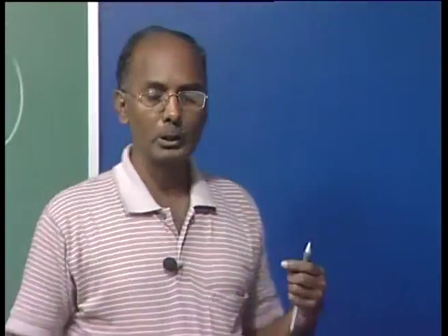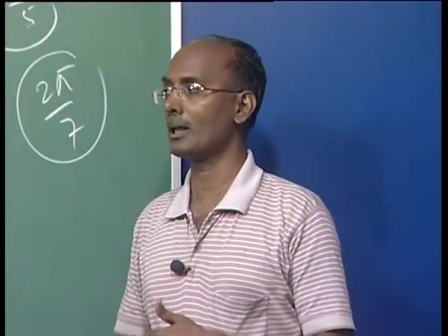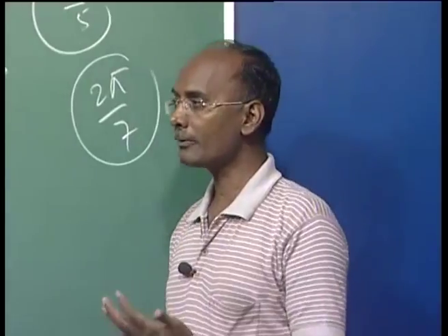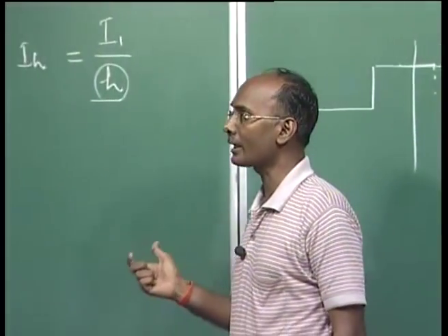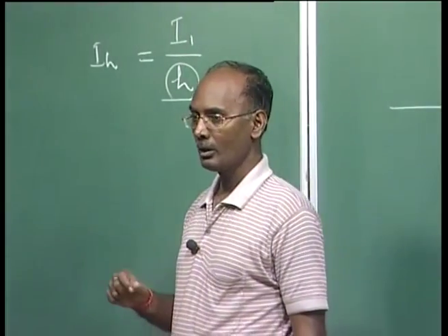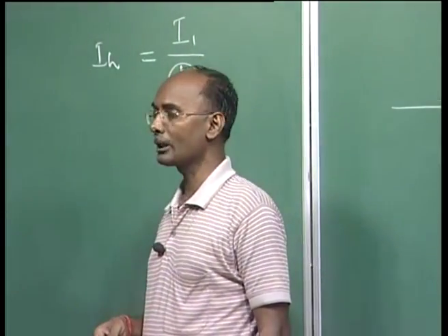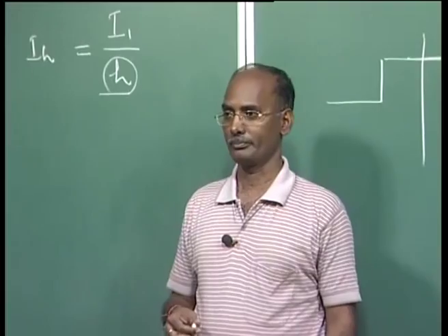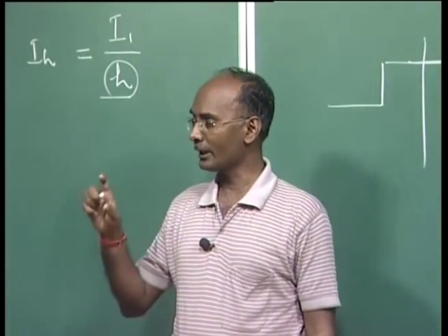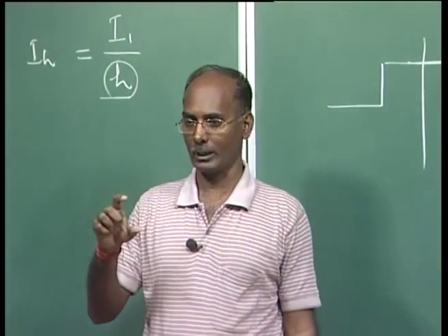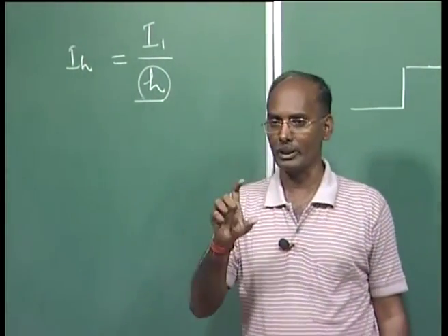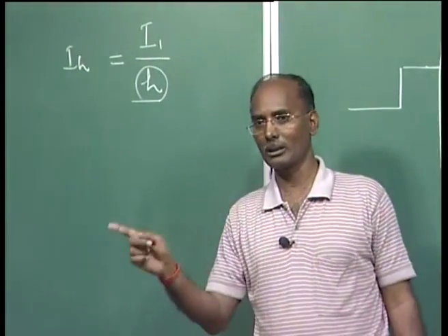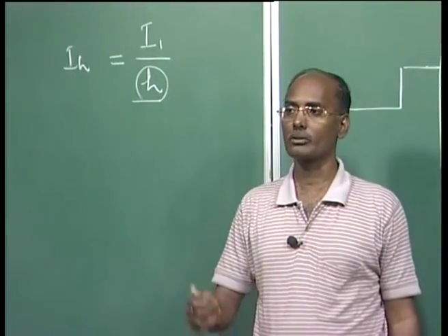So what we do, we use filters, and those are called harmonic filters. The purpose of harmonic filters is to reduce the harmonic voltage and current in the AC power network, and also to provide some reactive power support at that AC bus. If you are designing a filter for any harmonic, it will provide the minimum impedance for that harmonic, but for the fundamental component it will provide reactive power support.